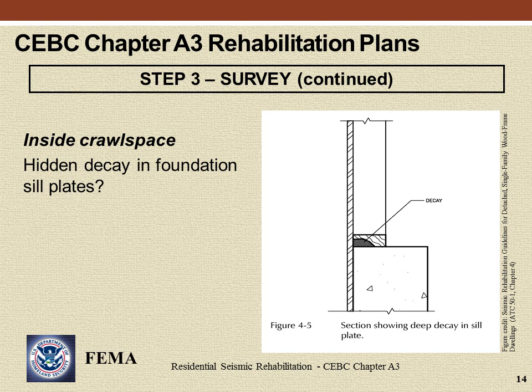Potentially hidden decay in foundation sill plates is an item of interest. ATC 50-1, Chapter 4 discusses the investigation of moisture content and the replacement of decayed sills. Probing of sills for decay damage extensive enough to affect anchor bolt strength is recommended. To be of concern, look for moderate to extensive decay in the immediate vicinity of anchor bolts or other conditions that would significantly affect the ability of the anchor bolts to perform.